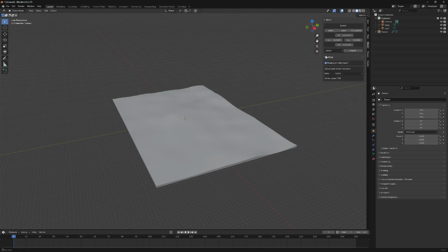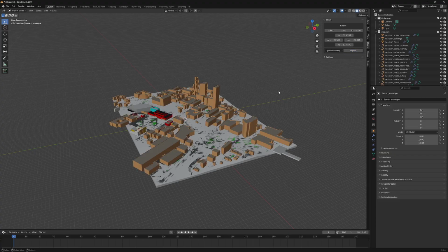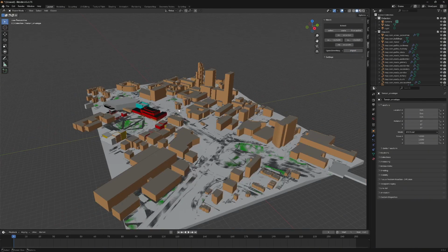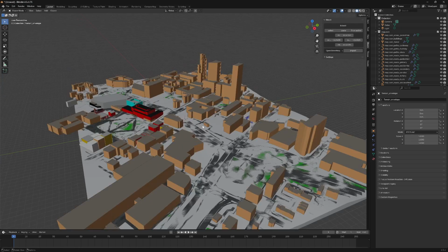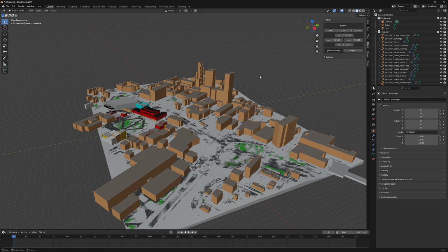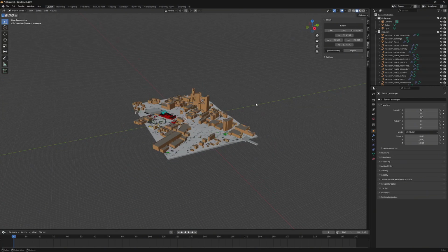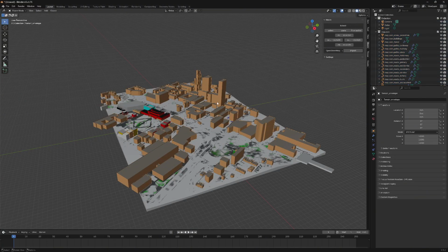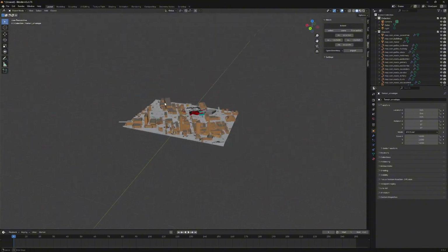So I'll go back to Blossom here. I've got the terrain. Now I want to do the OpenStreetMap. I can import that, and we'll just give that a moment, and it's going to download the OpenStreetMap information. And the way the OpenStreetMap information will come through, it will come through in a similar way to the way we set the APIs up from Google, but it's using OpenStreetMap information. Okay, so then I can use this, I can select it, I can navigate around my model, for example.